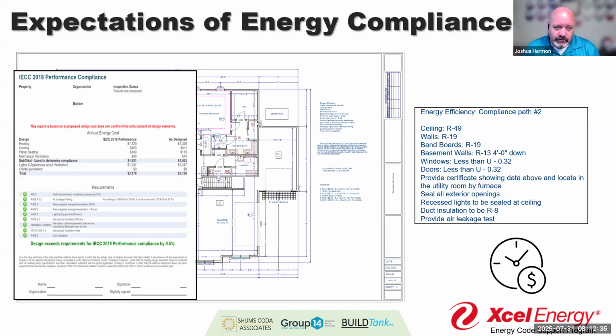Let me see what we got here in the comments. Consider orientation. Did not previously. Yeah. And we'll talk about that because it does change in the 21 orientation, especially in ComCheck. In the 24 version of REScheck, it starts to come in a little bit. If you input those values and don't add in your orientation, then it will kick you out as an error. So we'll talk a little bit about that, Francois.